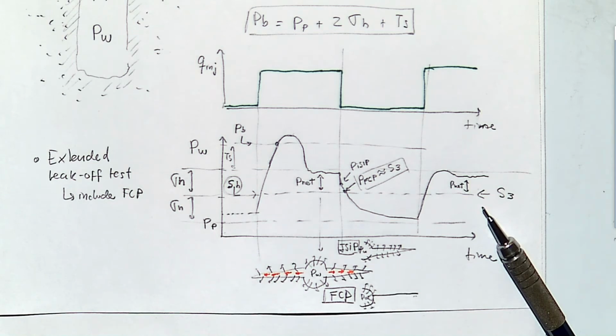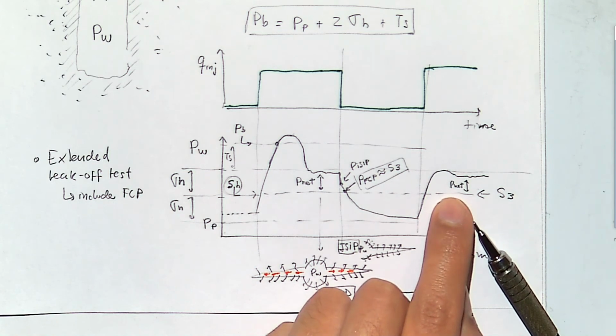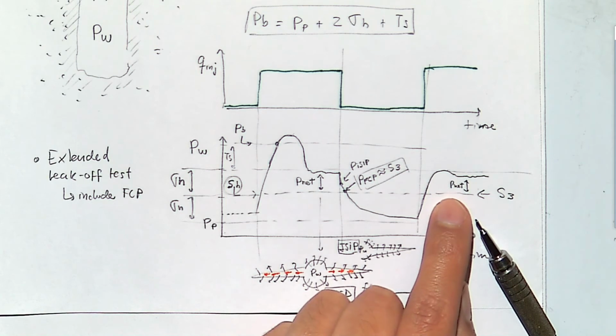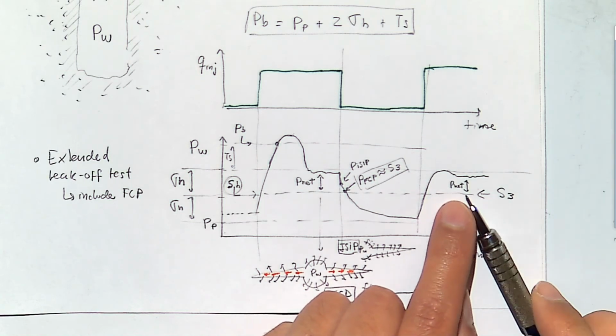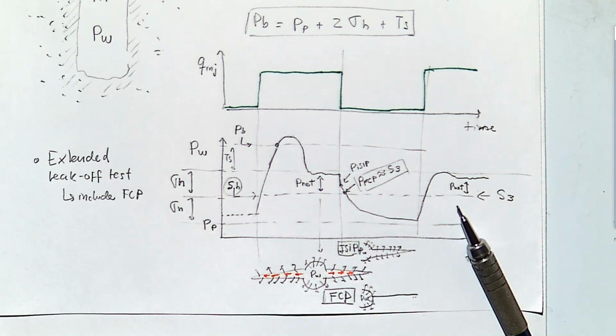It's not going to be the same to open up a soft rock than a stiff rock, and it's going to depend, of course, on injection rates and the viscosity of the drilling mud. The higher the viscosity of the drilling mud or of a fracturing fluid in general, the higher the pressure is going to be needed to circulate that fluid through a fracture.